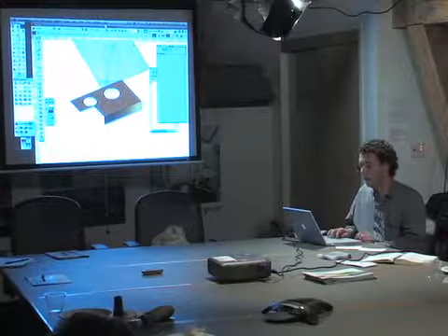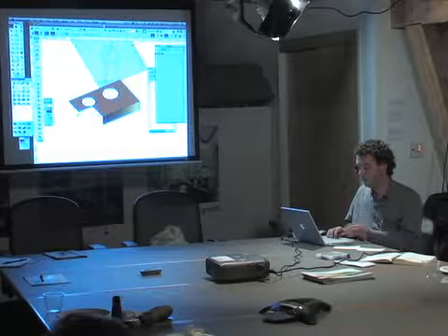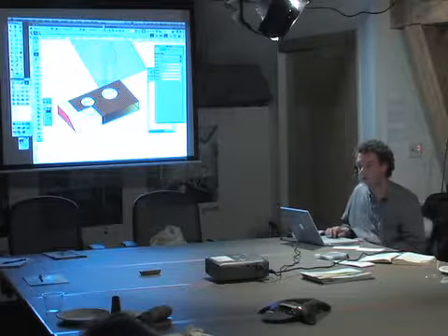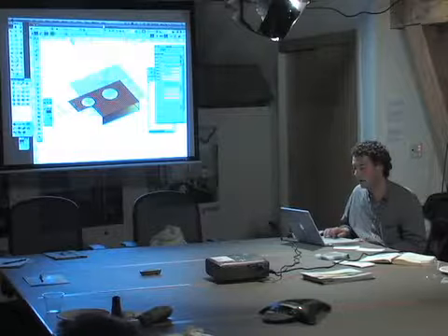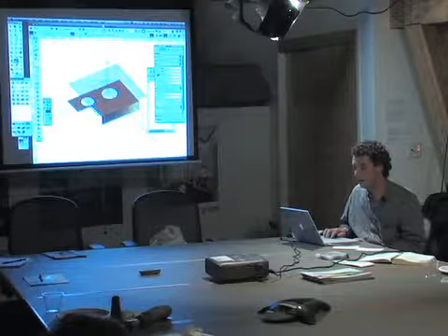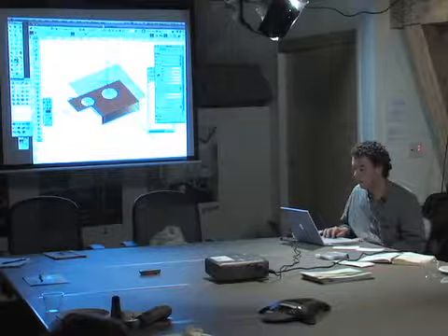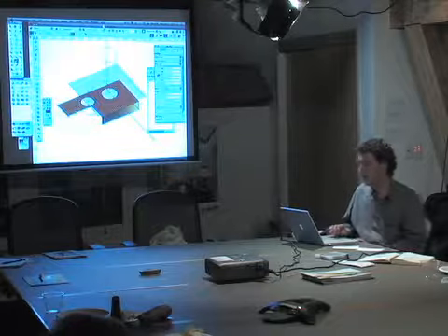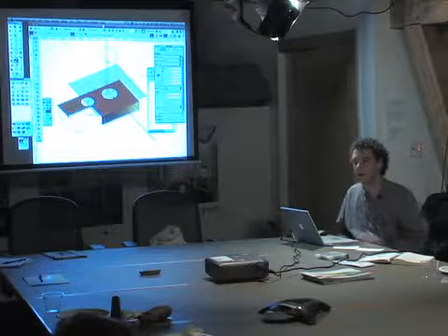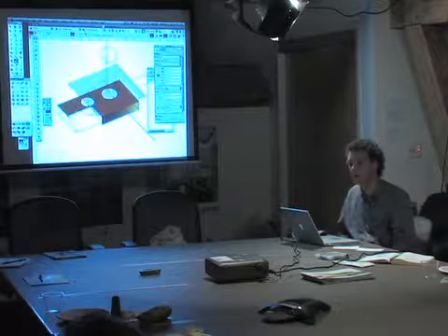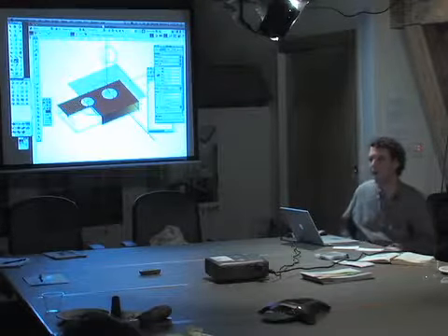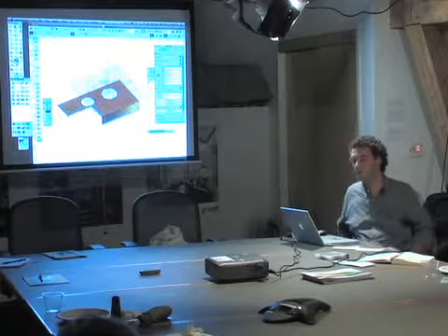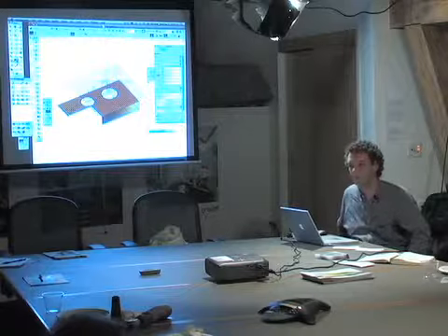But it is an extracted face, and if I go back to adjust this model, that face doesn't adjust. I'd have to go back and edit this polygon and readjust it, or it's probably easier just to delete it, re-extract that face, and reapply your texture. So it is just a polygon on the face of your model, so any changes won't be reflected in it. It's sort of the last step after you get your model created.